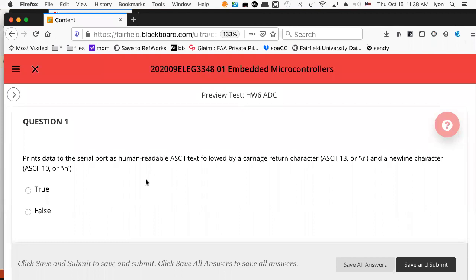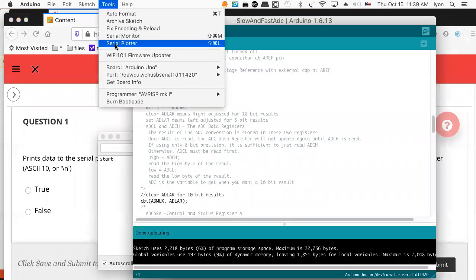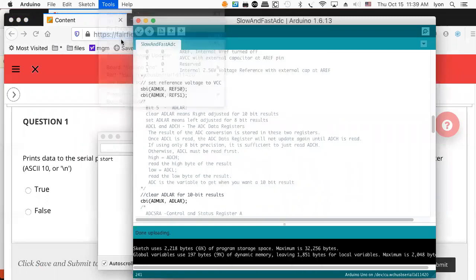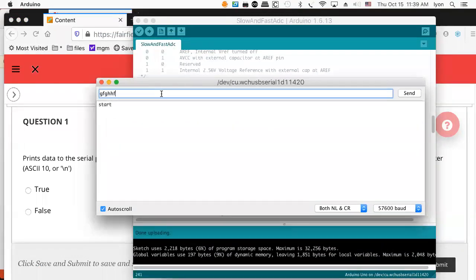But they've made it into modern usage. Moreover, when you go to the Arduino Monitor, and this is really maddening because it's still with us, when you input something and hit send, you can set it with a carriage return and a line feed, or just a carriage return, or just a line feed, or no line ending at all. And if your code is sensitive to characters other than the characters you're expecting, and it sees a new line or carriage return or both, that could throw the program off. So when you look at the monitor, it's quite important that you take into account that somebody could be sending a new line or a carriage return or both, or you should specify that no line endings are needed. Then when you go to get characters from the system, things will work properly. Otherwise, it'll be all messed up.